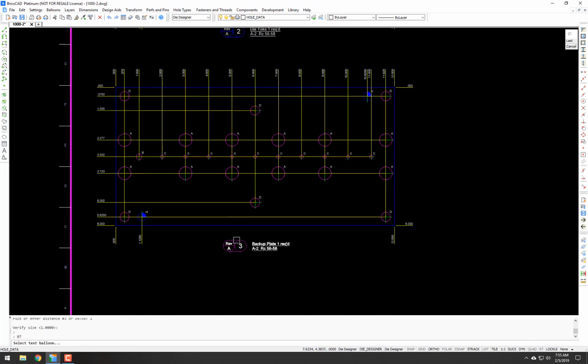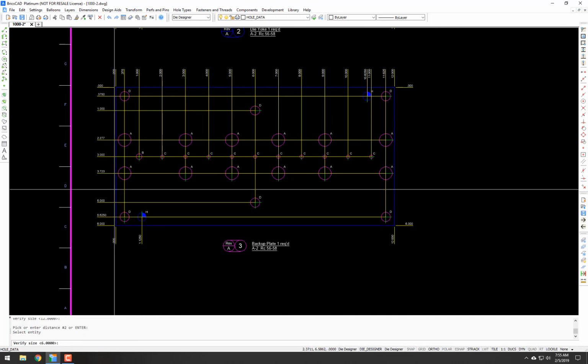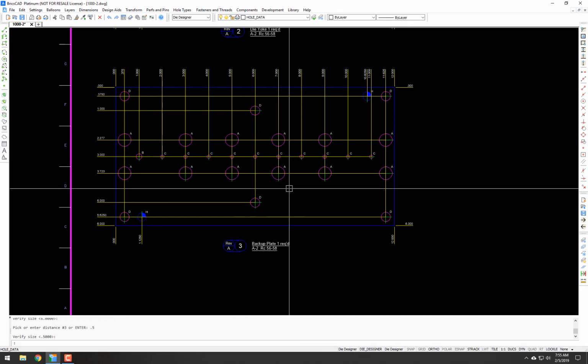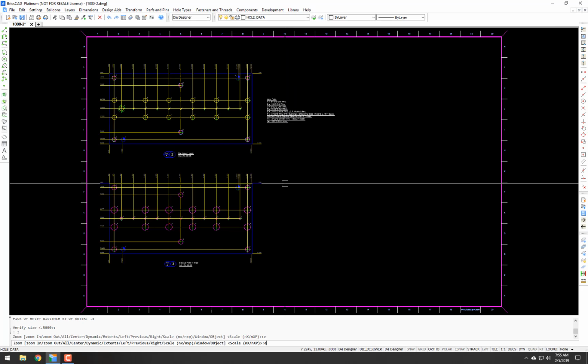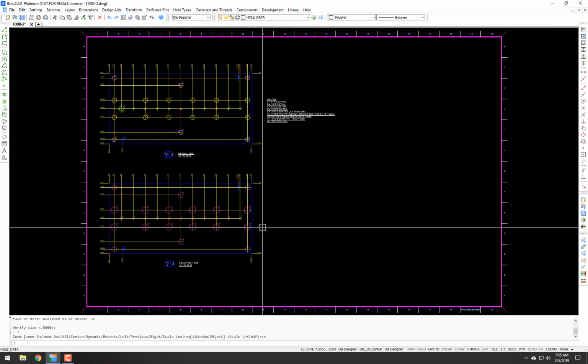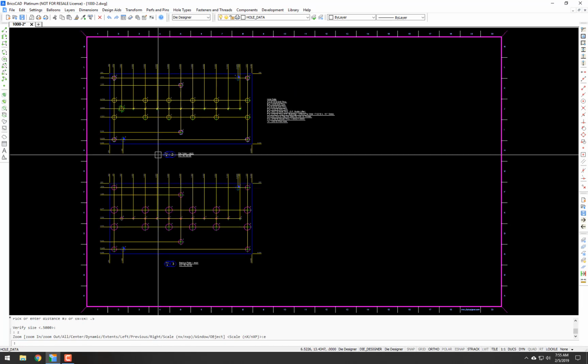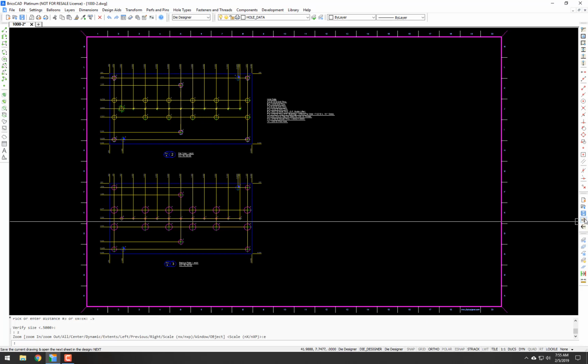Let's do the same thing for the backup plate. And I can't remember on the side view if it was a 1/2 inch or 0.375. I am going to say it was 0.5. I would X reference it in and measure it if it was a real design, but it's not. So, anywho, that's detailed, dimensioned, hole charted, and ballooned.